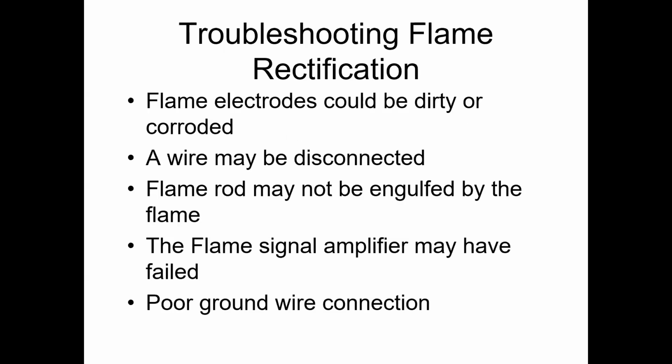So, troubleshooting flame rectification, again, flame electrodes are going to be sitting in a flame. So they're going to get dirty. They're going to be corroded. You're going to have it where they can build up soot on top of them.